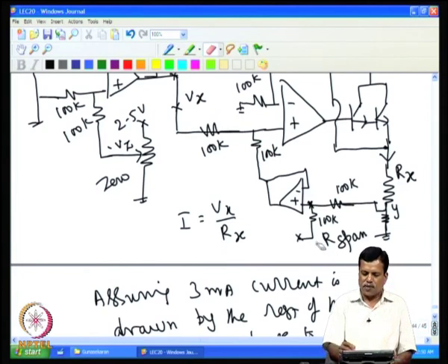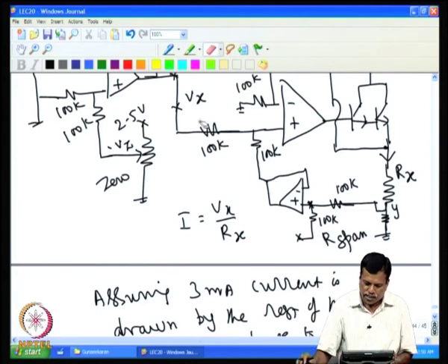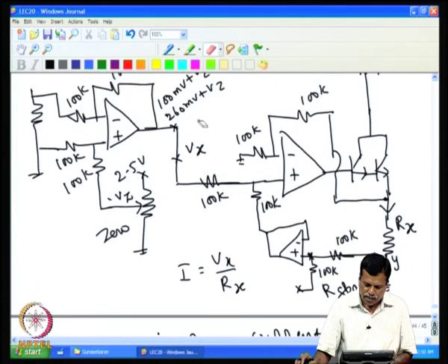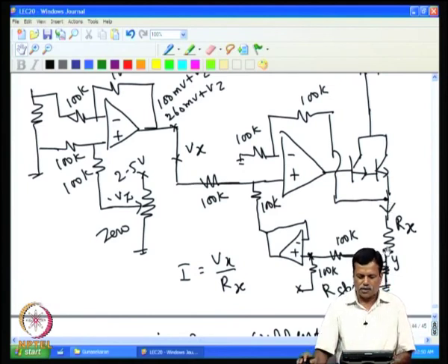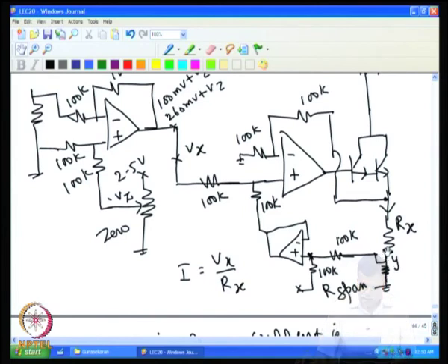If minus voltage was there, one could have subtracted the voltage here. Now, another possibility is to keep this voltage as 0, and then you will have only 100 to 260 millivolt varying, and that can be made to vary 4 to 20 milliampere, that is another possibility.